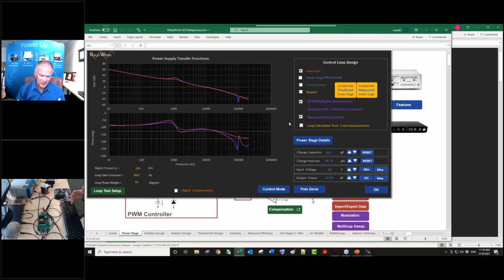One of the things we have to teach people in our lab is, when you have these cables on your bench, most people have a lot of junk on their bench too. And the power supply moves forward and then the cables drop down into their lap. Not a good idea. We try to push the cables back onto the bench, because if you stand up and you grab a cable and it's a high voltage power supply and it lands in your lap, it's fun for people to watch, I suppose, but not to do. Okay, so there you go.